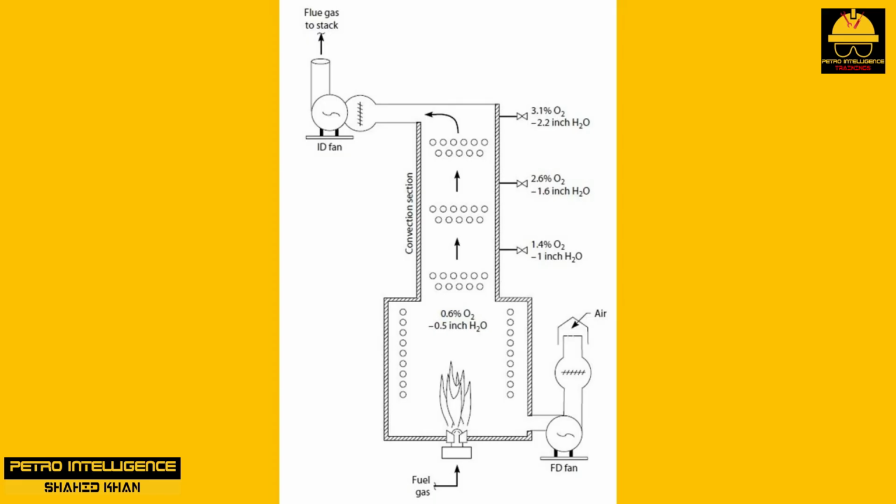This boiler is puffing, too. Perhaps I should have shown its convective section walls alternatively convex and concave, but instead I have just entitled it the puffing boiler. Here is what actually causes the puffing, vibrating, or thumping. The fuel gas is not properly combusted at the burners, so partially combusted hydrocarbons and perhaps some totally unburned fuel pass up into the convective section with the flue gas. The convective section, as shown in picture, is under negative pressure, so air leaks in and mixes with the hot unburned hydrocarbons, which then reignite. Thus, we have afterburn in the convective section.